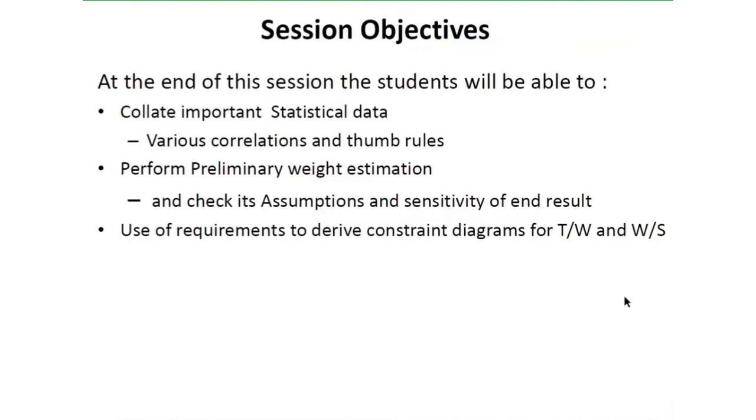Just as a matter of interest, the thrust to weight ratios of most combat aircraft are close to 1. Some of them are more than 1, some a little bit less than 1. And for long range passenger aircraft, the thrust to weight ratio is somewhere between 29 to 33%. Because in a commercial transport aircraft, the fuel consumption, and hence the cost of running the aircraft, in terms of dollars per passenger kilometer, is very, very important. They would rather have as low thrust as possible, because passenger aircraft are not expected to do very steep turns or dive pullouts and so on.